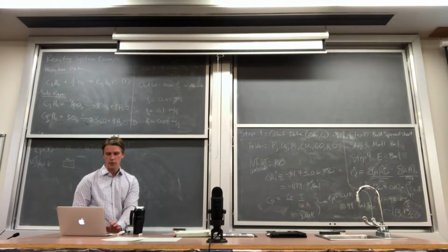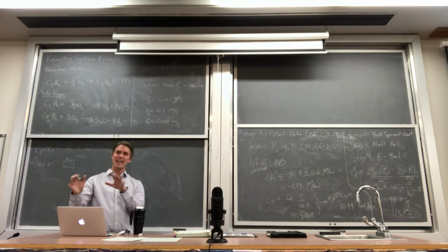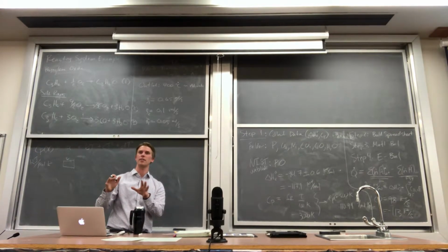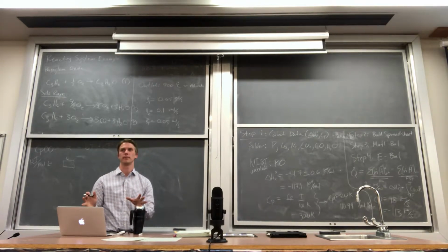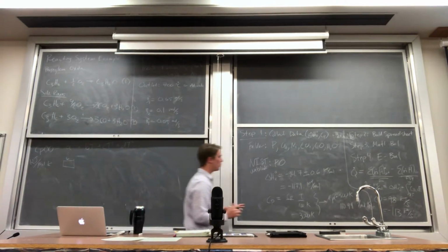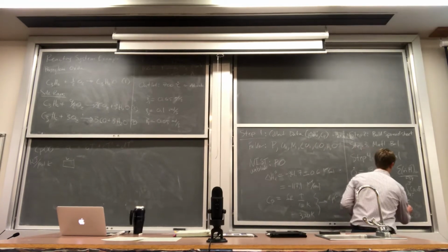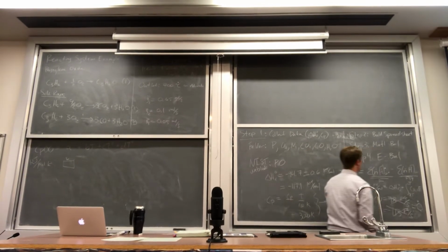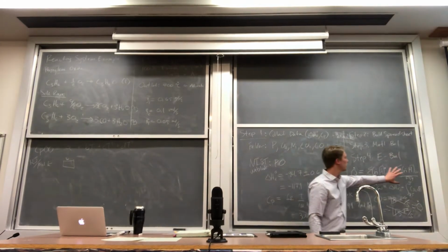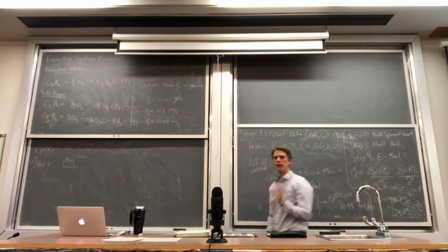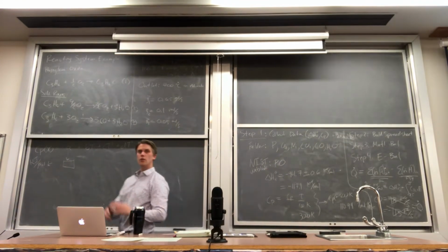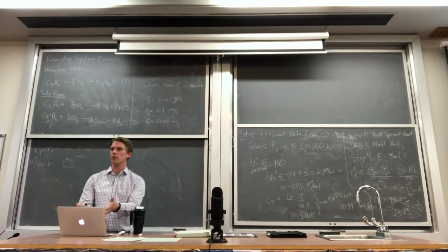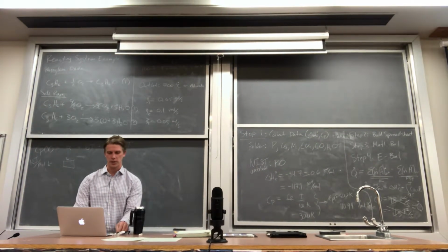Now let's say, instead, I want to solve this as an adiabatic process. If I'm solving this as an adiabatic process, I'm going to say that Q is equal to 0, which means that the enthalpy out has to exactly match the enthalpy going into the system. And this is no more difficult than just setting up a solver inside of my spreadsheet here.